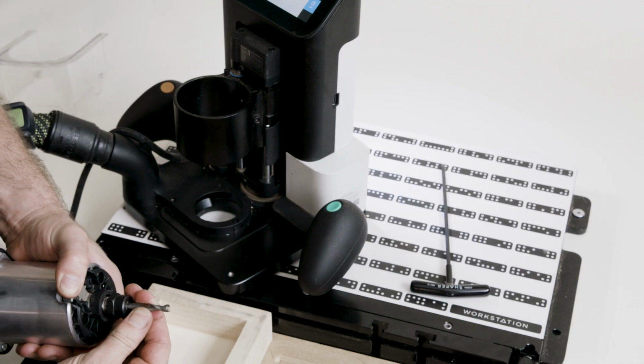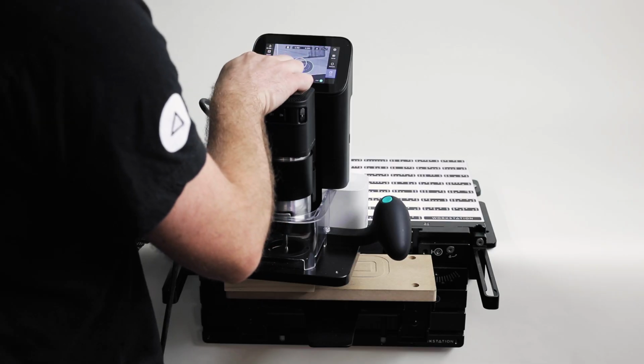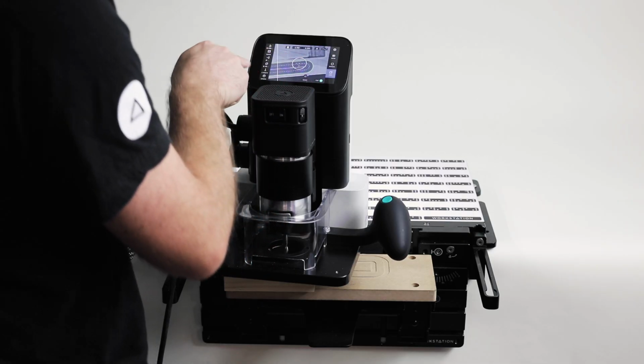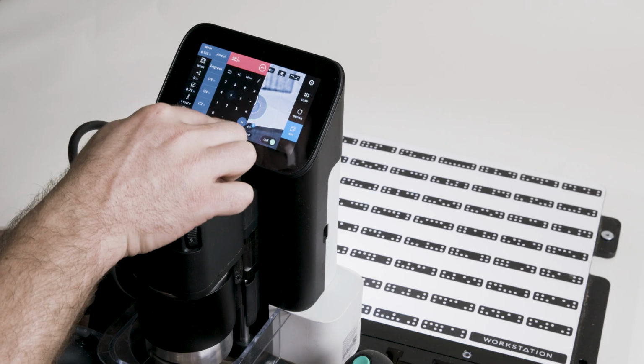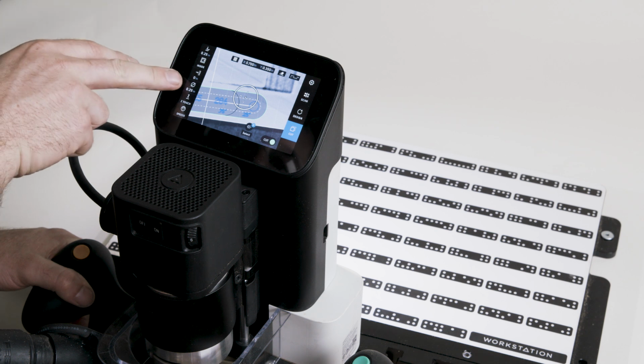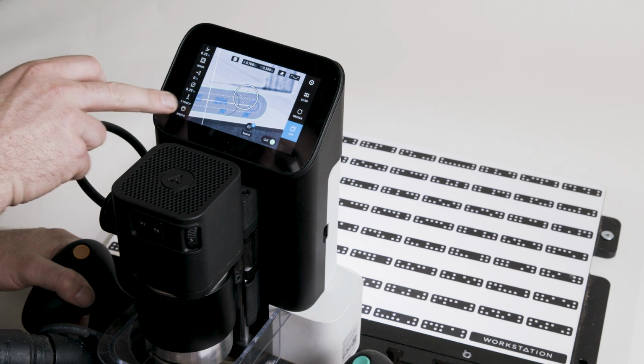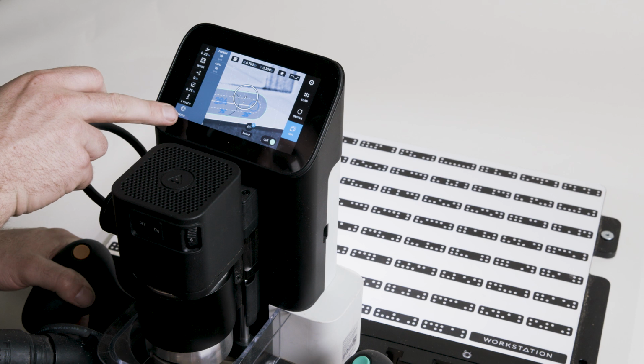So I'm going to put my cutter in and cut this out. Now it's just a matter of entering the relevant depths. So my cutter diameter is correct. My depth, I want 0.25, done. So I'm cutting to the right depth, right cutter diameter. We've done a Z-touch. Double check my speeds. We're good.